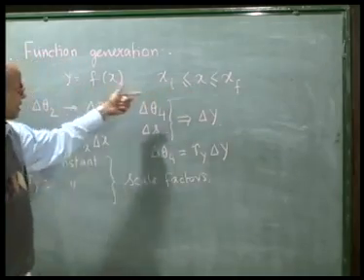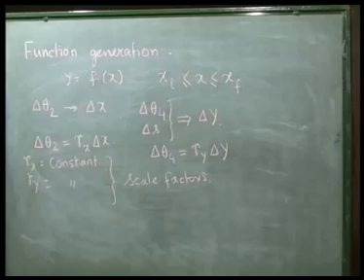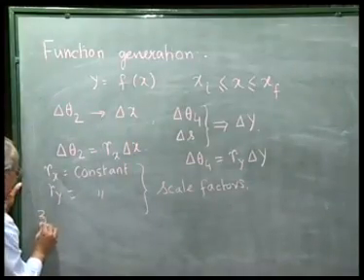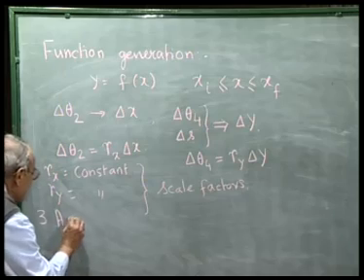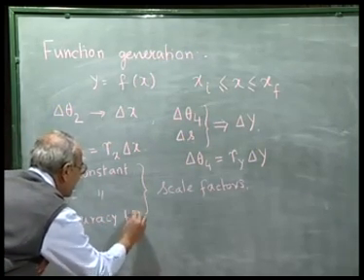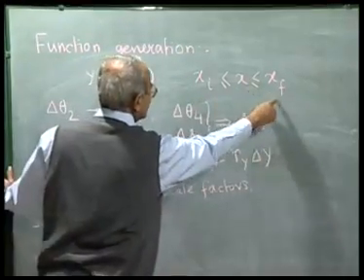In this precision point approach which we are discussing in this entire course, what we mean is that I cannot generate this function in the entire range. So, we take some accuracy points, and as the first choice I said we should take the Chebyshev's accuracy points, where, suppose for 3 accuracy points, I should take x1, x2, x3 in this range.